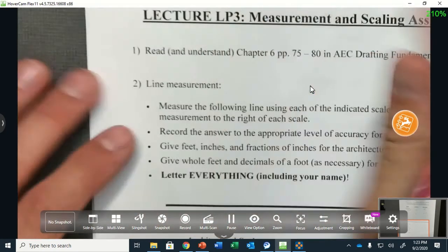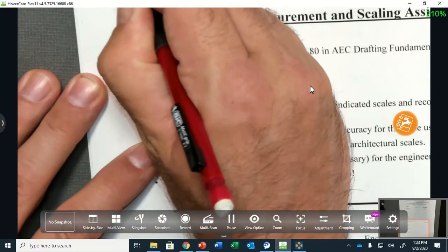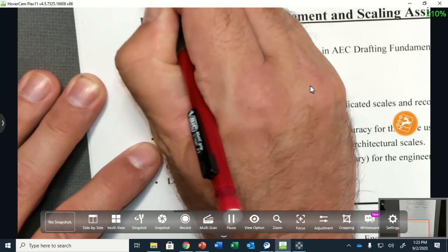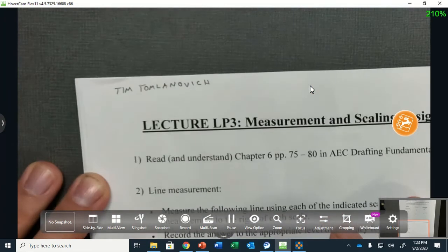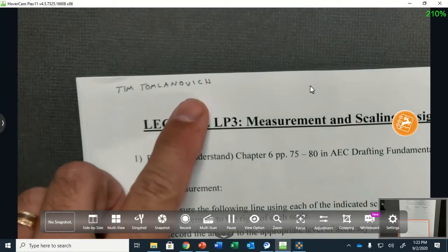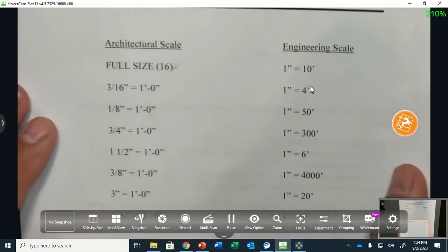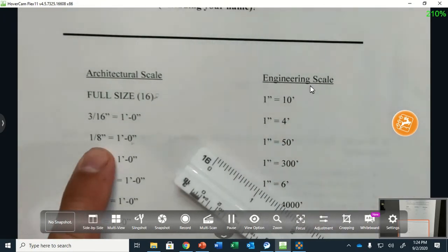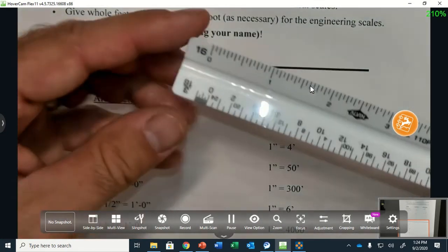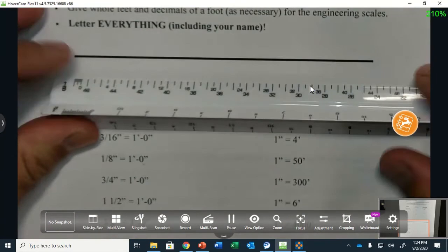You're going to put your name up here, right? And letter it. Okay, nice and neat. Well, mine's kind of crooked. I'm trying to look and make sure you can see what I'm writing, which you couldn't see, so sometimes it helps just to tape down your sheet. All right, architect scale. 1/8 inch equals 1 foot, so architect scale. I find my 1/8 inch, put her on here.